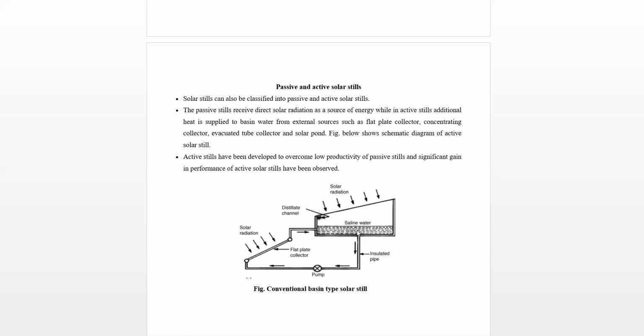Now in this case, you see the power requirement of this pump is very low, because the water is to be circulated with a very low flow rate, so that the water gets enough time while it passes through the solar collector so that it can be heated, right? So a very low flow rate is required, so a very low power pump is required, hardly a 60-watt pump.